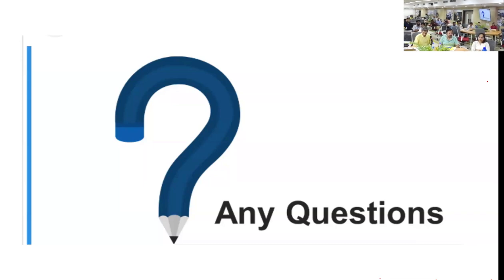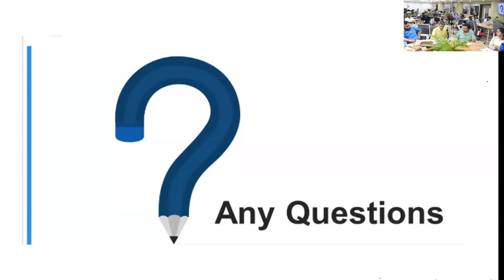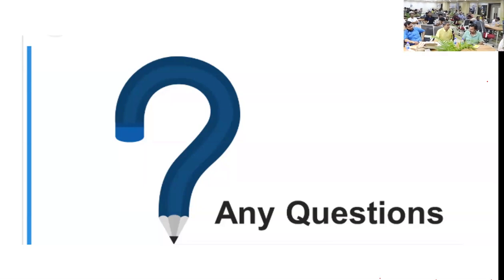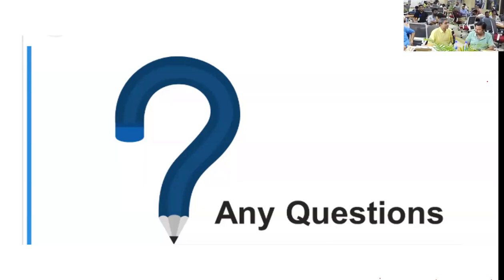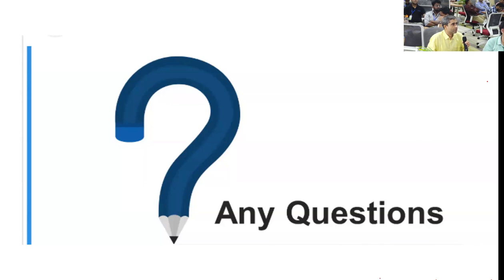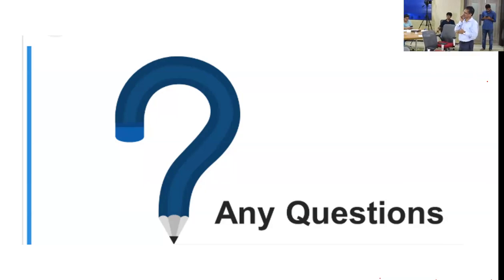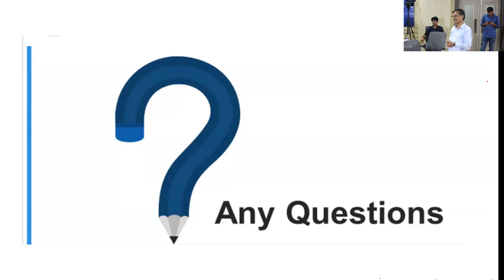Okay, sir. And sir, you discussed one more point, that when there is no water in the clay, Terzaghi's theory is not applicable for consolidation. No, I said when it is unsaturated. Terzaghi assumes that the soil is saturated, so full, that is zero air voids, only water. But that is not the case in most of our cases. In the field, we will not achieve that. So that's why I said there is another concept called unsaturated soil consolidation.